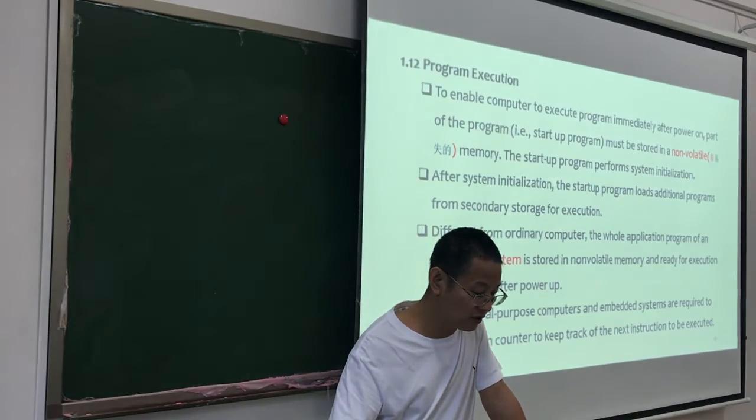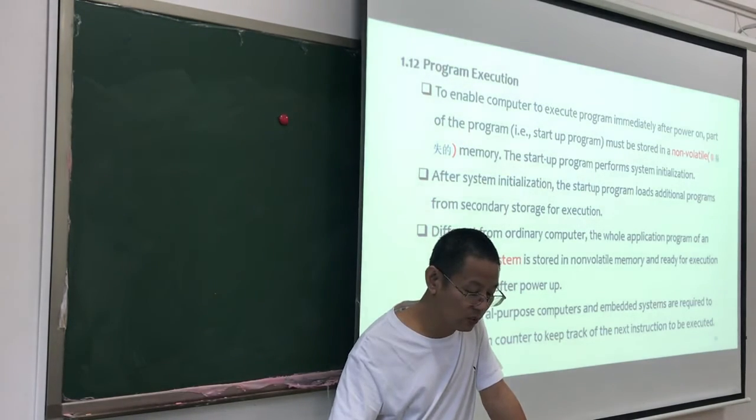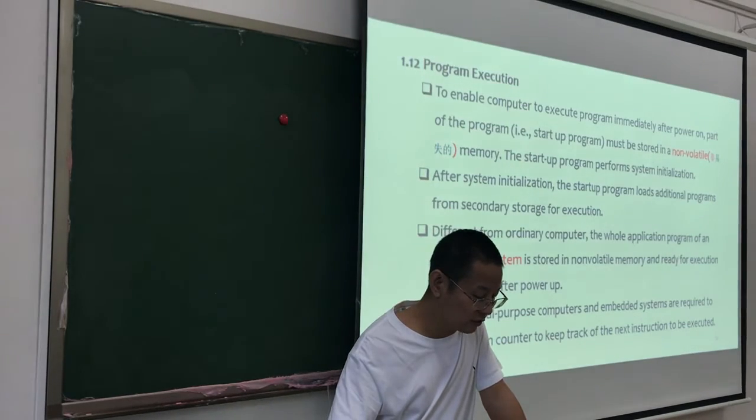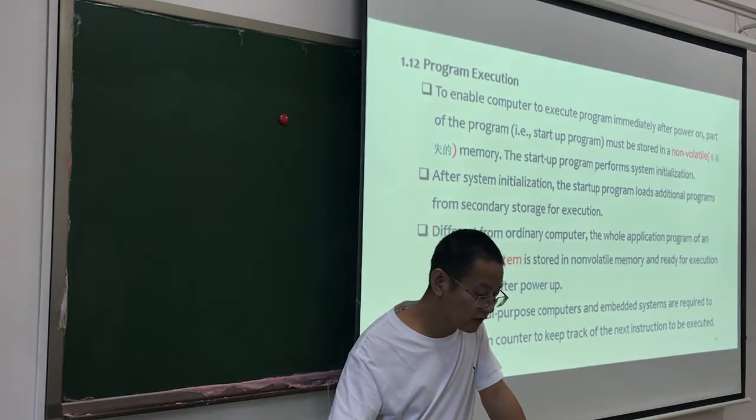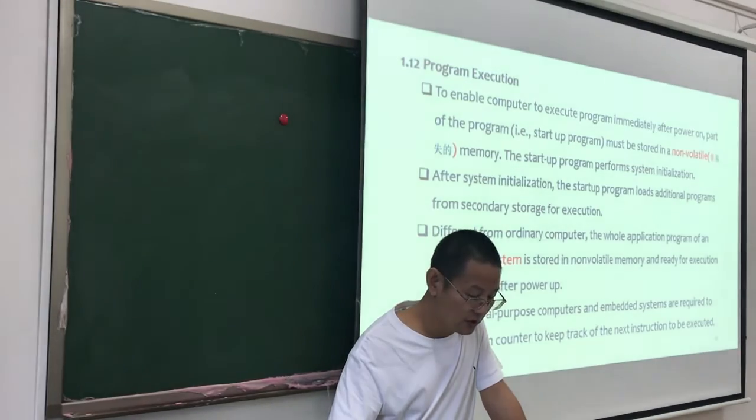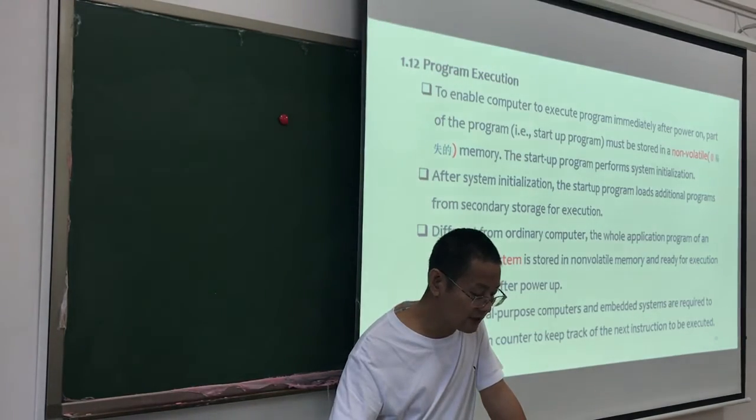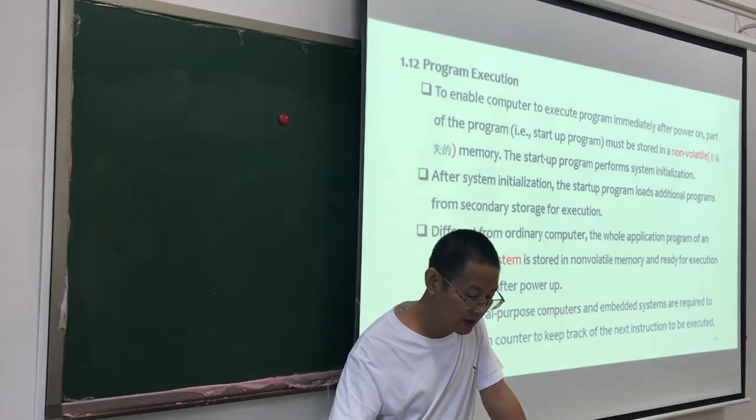After system initialization, the start program loads additional programs from secondary storage for execution. Different from an ordinary computer, the whole application program of an embedded system is stored in non-volatile memory and ready for execution immediately after power on.